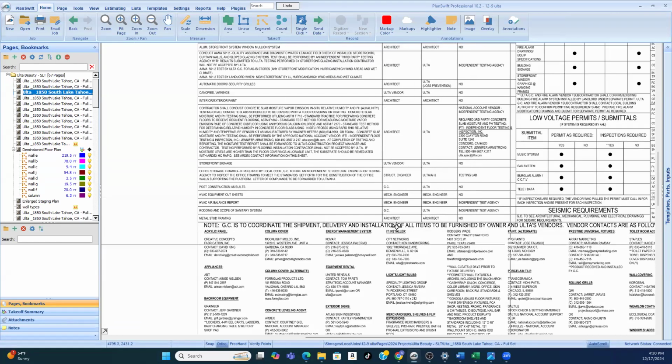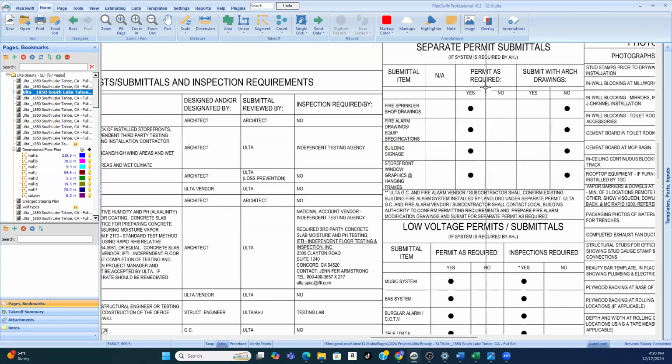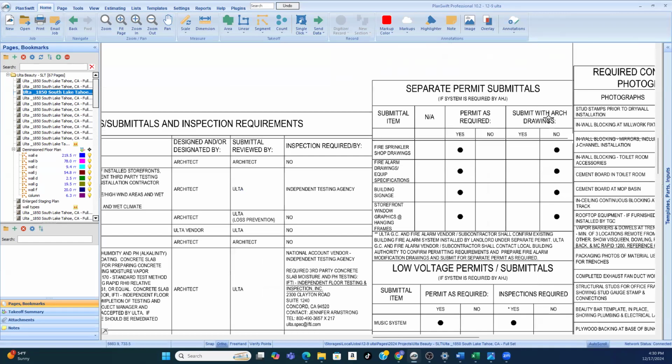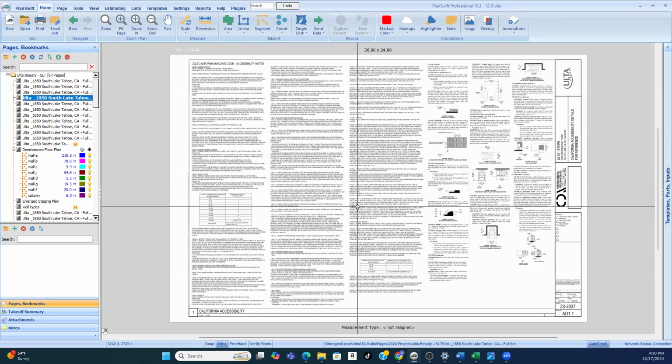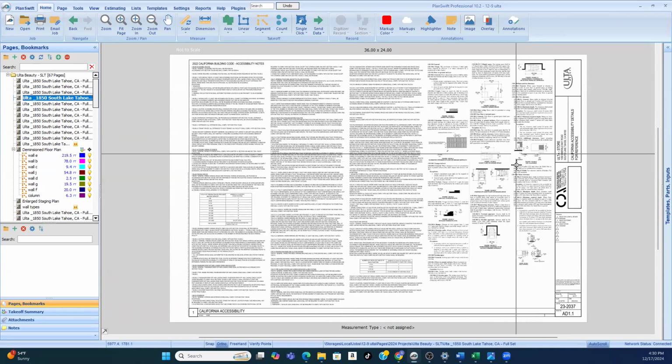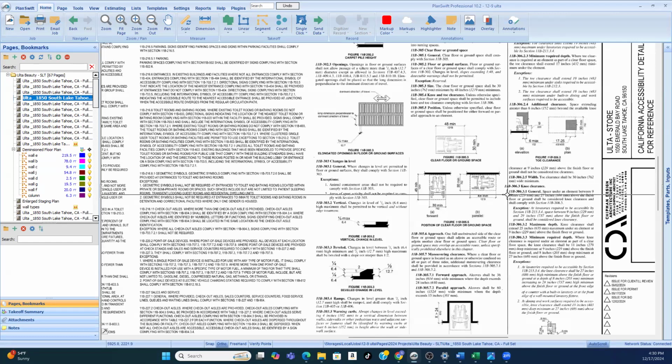So look through that also in good detail, whether they require a submittal, yes or no, and what the submittal is. A sample of whatever it is they're asking for, they'll ask you to submit it to them. And two, there are guidelines that apply to the receipt and transferring of submittals too. They're supposed to give you a certain amount of time to send them, and they're supposed to respond back to you if it's adequate within a certain amount of time. And if it's not, you have a certain amount of time to get back with the right thing. So there's a process to everything.